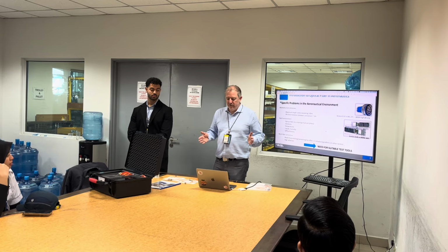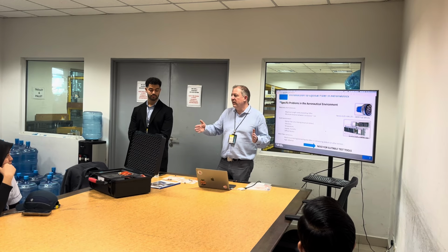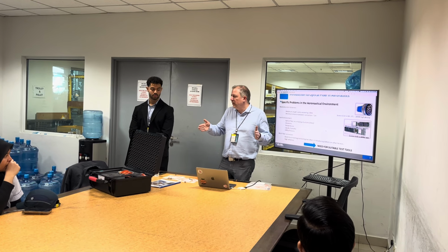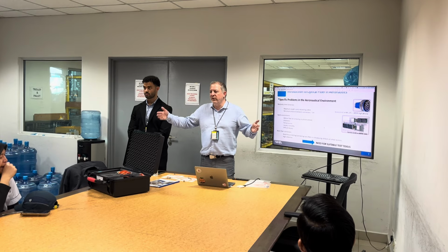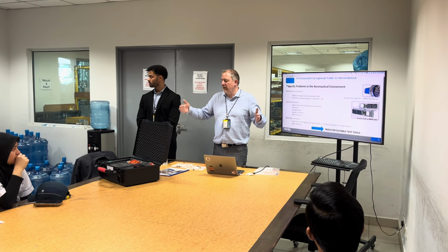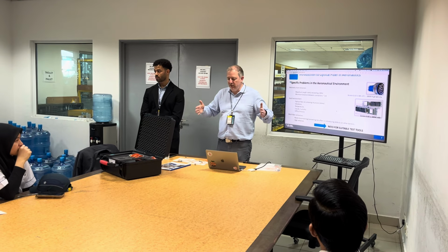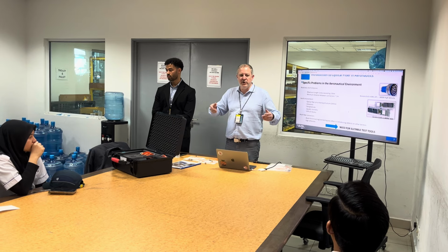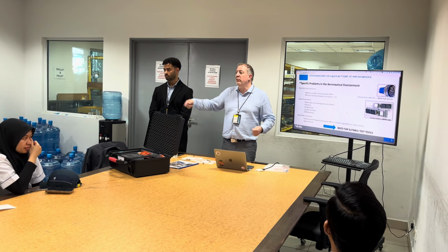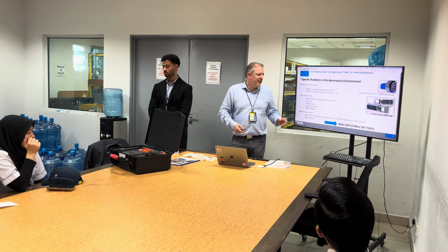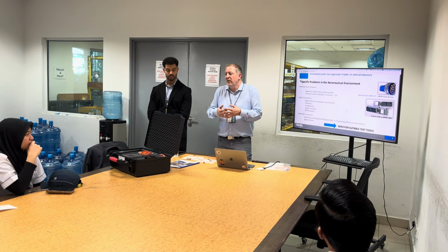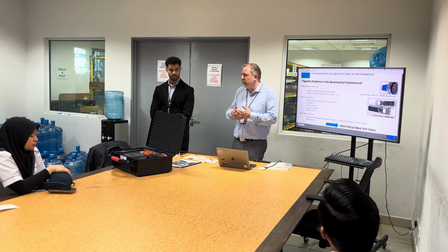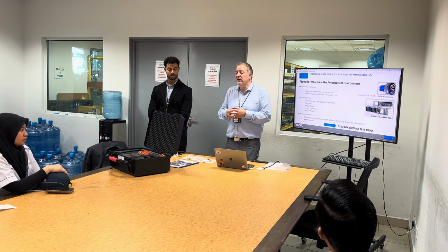Compared to telecommunications, sometimes you have interconnections. You never have two connectors within a distance of 1 meter. Still, you may have a lot of connectors on the way, because the plane is built by section, and sometimes the fiber is installed before they assemble the sections, so they assemble later. So you can have multiple connectors on the way, and this is important to mention because this is mostly the area where you may have issues. Before you get a broken fiber, usually you will face connector issues.